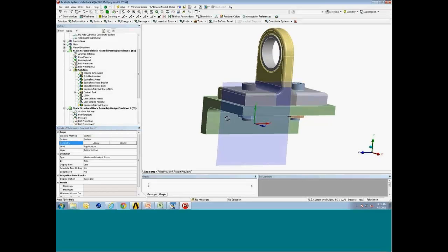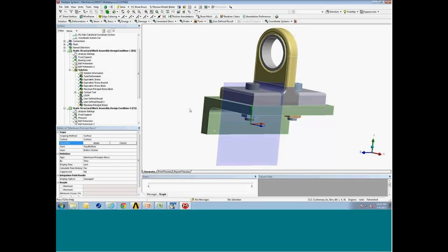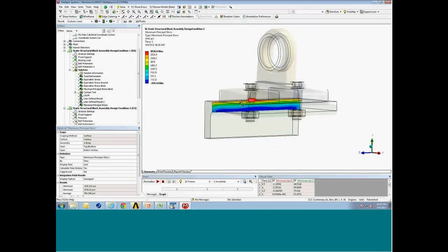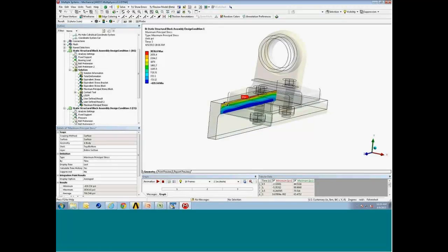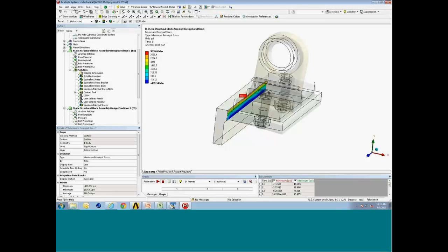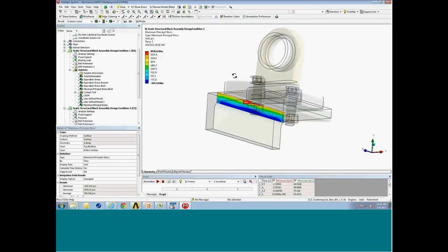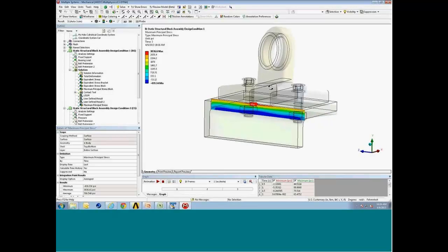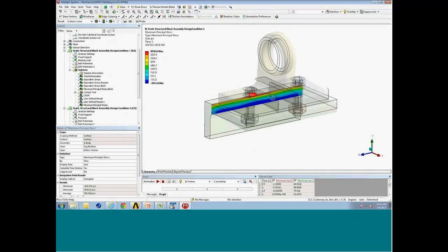You can scope it, again, to specific bodies if you like. So let's go take a look at a section cut through this bracket. And once we've defined that surface, we can evaluate that result. It'll go in and map, interpolate those stresses onto your surface. So that allows you to map. With pulling on this bearing, you can see the bending, the principal stress in bending.